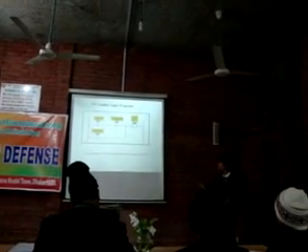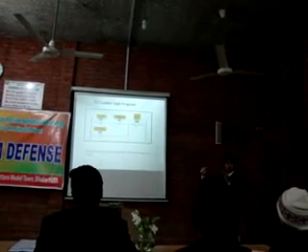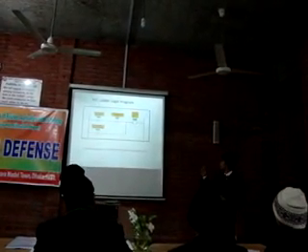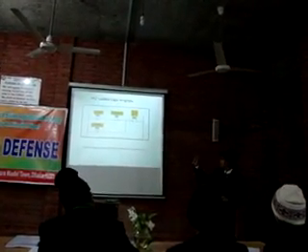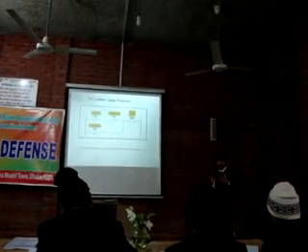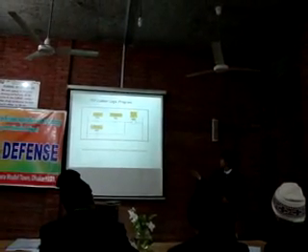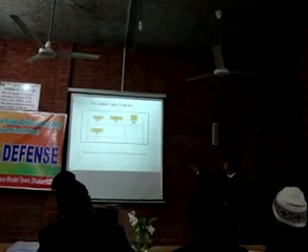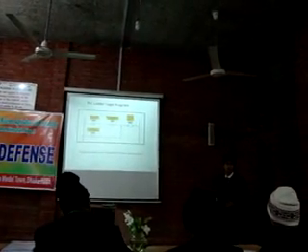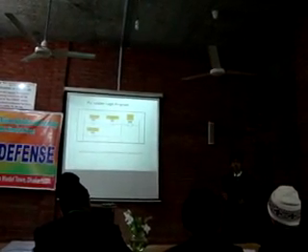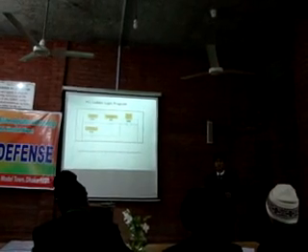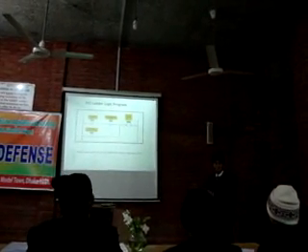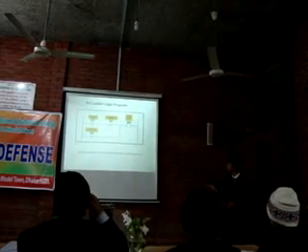This is how it's programmed. These symbols are in the programming software, and we have to click those symbols and put them into the script, and this is how ladder logic programming is done. This is not conventional C programming. If this input happens, then do output. This is the ladder logic program this way.